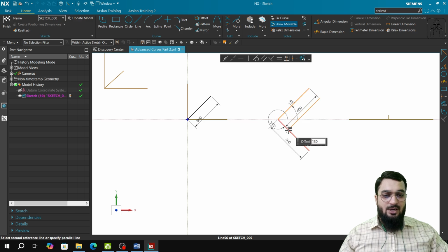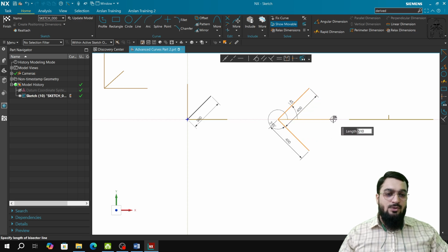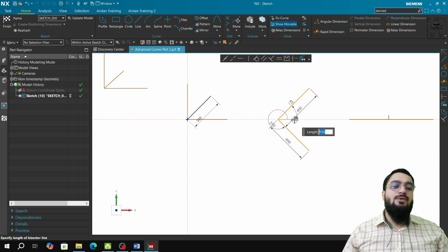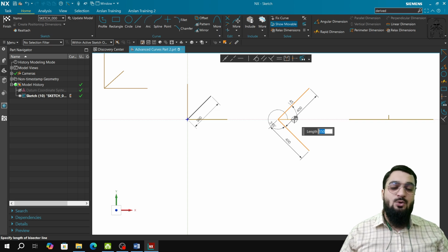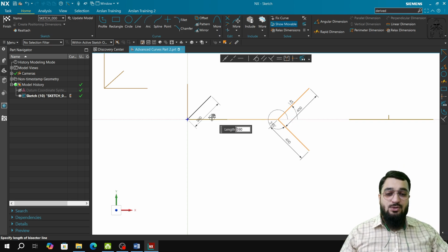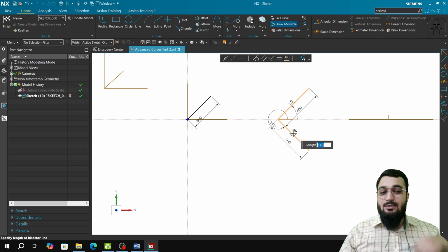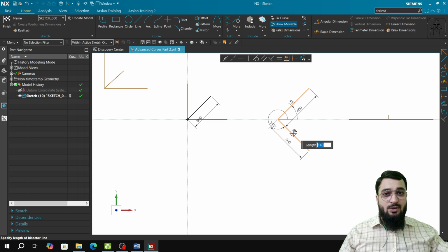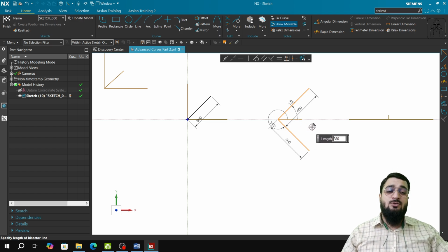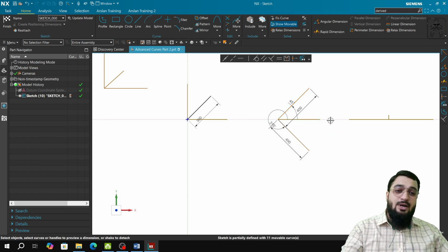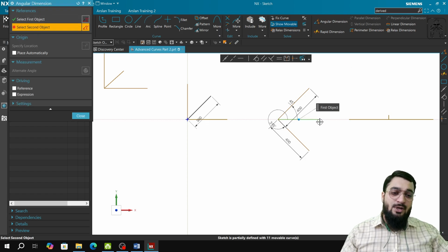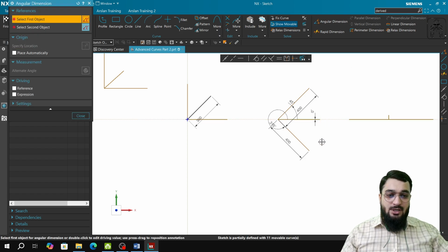After that, let us get what the result will be for the second example. I will select this line and this line, and you will see that it is getting at 0 degrees, because 45 and minus 45 will give you 0 degrees. As I told you, only the concept of angle is used. If something is at 0 degrees and 90 degrees, then 90 plus 0 divided by 2 is 45, and 45 plus minus 45 is 0, divided by 2 will also be 0. So this will be the derived line. You can also check the angle if it is 0 or not, and you will see that it is 0 degrees.